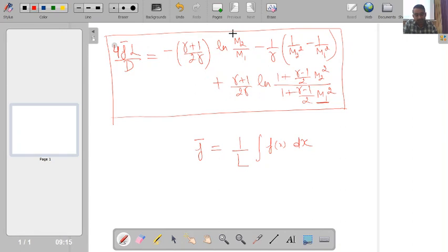Now, along with this downstream Mach number, we also have to determine the other properties such as density, temperature, pressure, stagnation pressure and stagnation temperature. Okay, so these other properties we also have to determine at station 2. At station 1 we are considering that these are known to us, and then we have flow inside a pipe where friction is involved, so that friction will change all the properties at the exit point. So we now need to determine these properties.